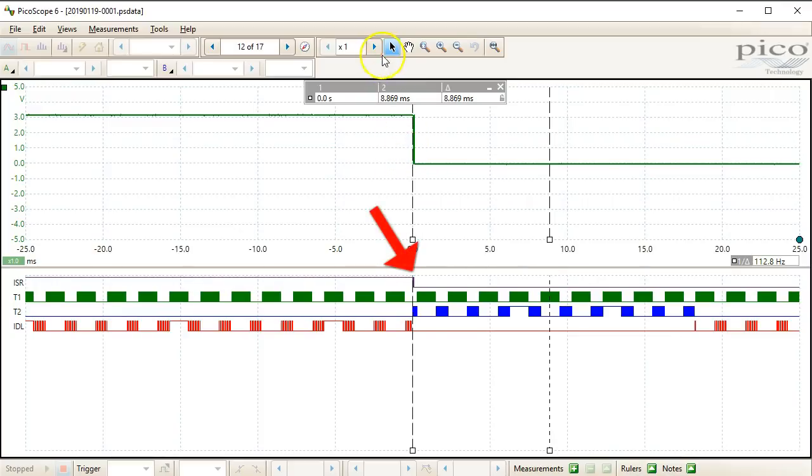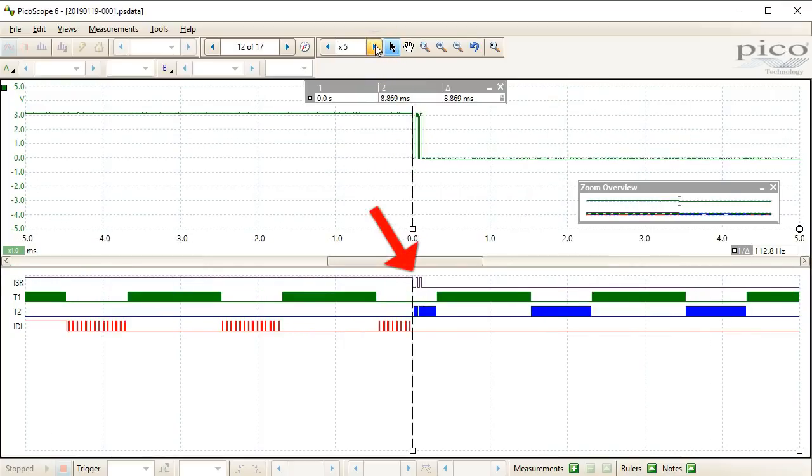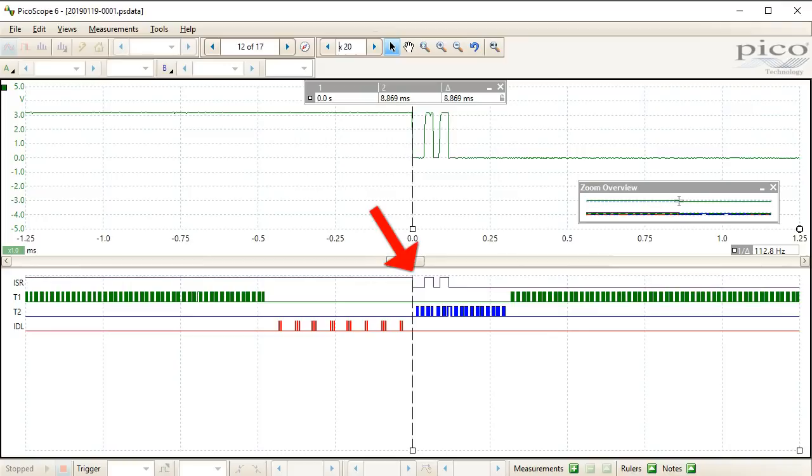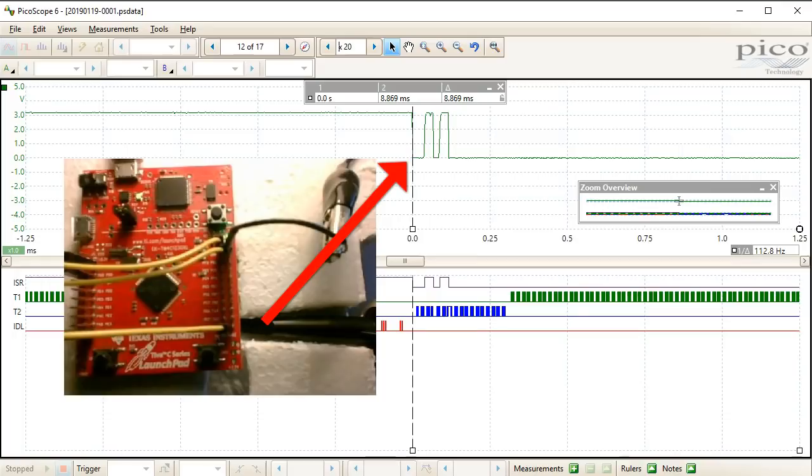Well, when you zoom in, you can see that the falling edge of the ISR line is not clean, but rather shows some strange spikes. These spikes are even better visible in the analog waveform of the same signal in the upper part of the plot, which I specifically provided for today by probing the PF4 pin from the bottom of the board.